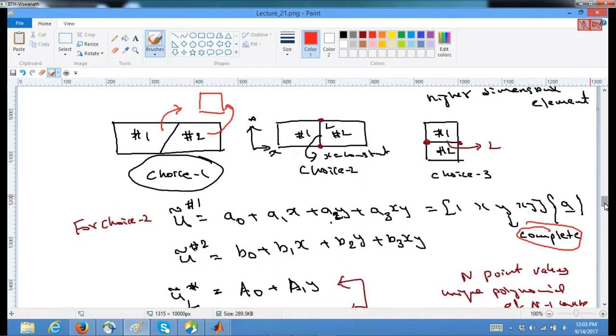So that is one way, and there are some adjustments you can do to get the things right along the boundaries, that will also ensure it. Or just making sure that you have horizontal and vertical boundaries will also do that, but this is uncontrollable in all the generic scenarios. So it is better to go for the isoparametric formulation.